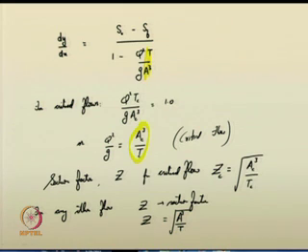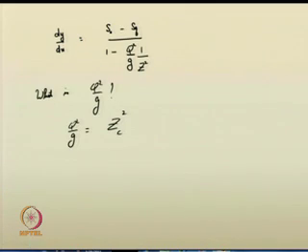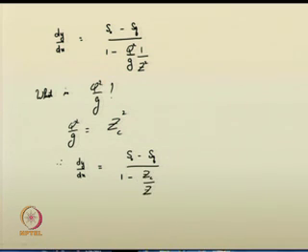So, substitute this thing. Now, this is q squared by g, you can substitute those things. So, you will get the following relationship. Therefore, your dynamic equation becomes dy by dx is equal to S0 minus Sf by 1 minus Zc by Z whole square, right.